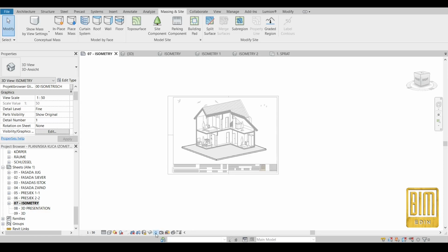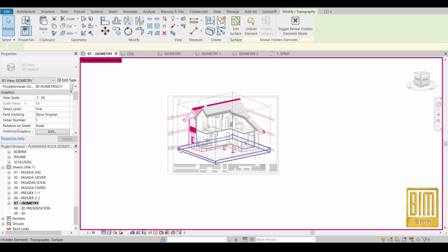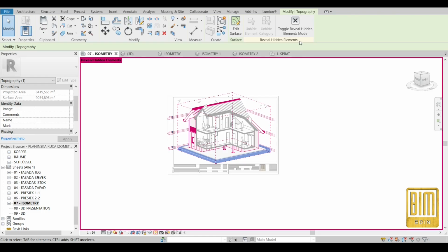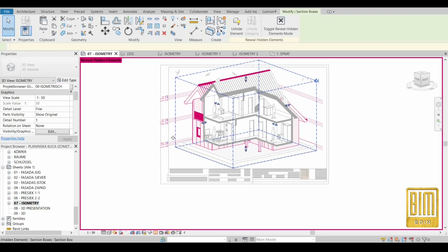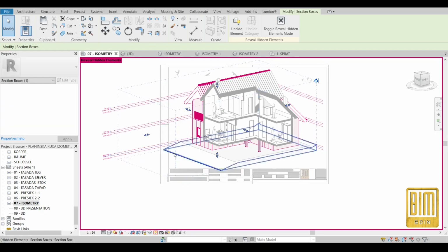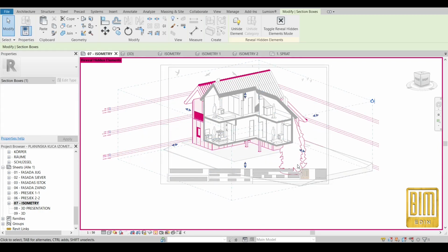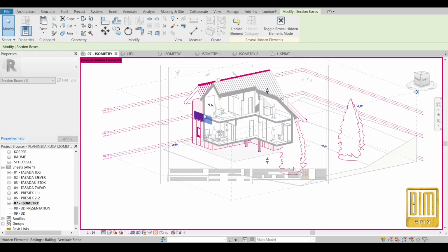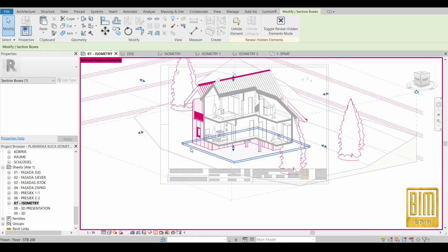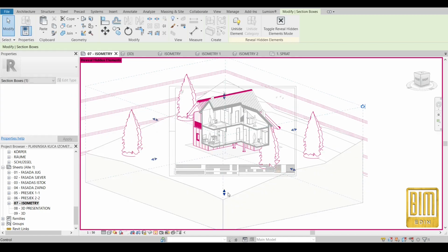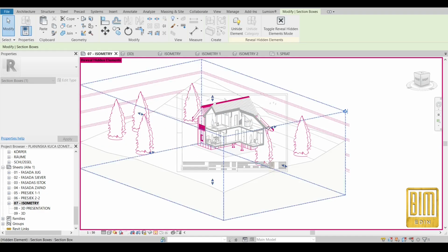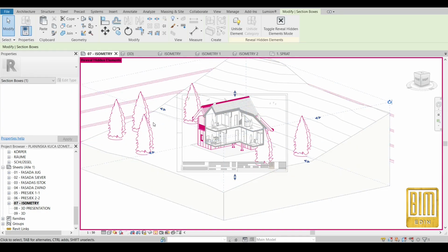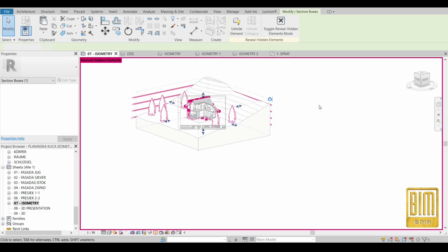Just one more time, I would like to repeat that the 3D views must be locked and have the same orientation, because we want them to be in the same place. Every next view must be in the same place where the previous one was.